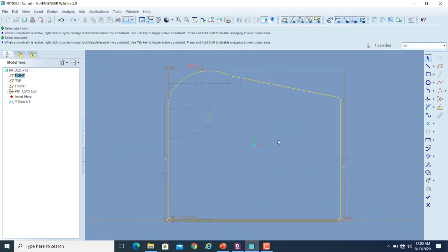So it will change to the active dimension. So now these are the weak dimensions which are dull in color. And once you come out of the sketch command, so automatically those dimensions will become permanent. So otherwise you can use your own dimension manually also. So if you look into these tabs, dimension tab is also available over here, and if you click on that arrowhead, so these are different modes of dimensions that you can use.